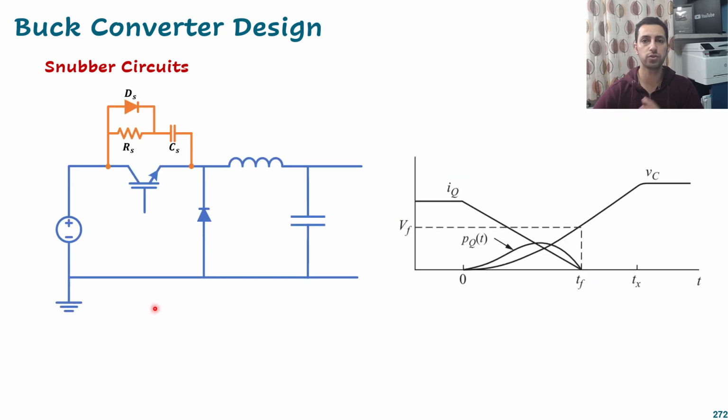And now if we look at some equations as guidance for our snubber circuit, we have here the buck converter, and I just attached the snubber circuit across my MOSFET. Also, I want to say that the snubber circuit is not designed for just MOSFETs. You can really put some capacitor and resistor across the diodes as well. You don't need another diode, but you need at least resistance and also a capacitive component across that diode, because this will reduce the EMI and also the spikes.